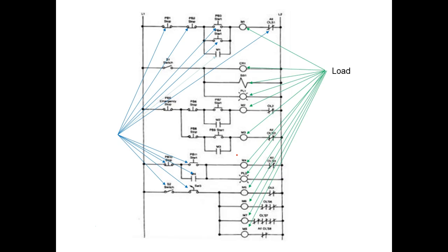So this is a typical relay logic symbol. So this is a rung. But it's parallel, right? Understand that. So here's a circuit that runs from L1 to L2. This is a rung. So we do have a lot of parallel circuits. It's going to be a one load series circuit, or it's going to be a multi-load parallel circuit.